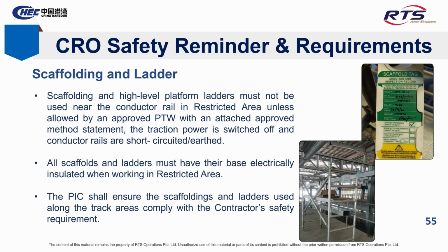Slide 55, Scaffolding and Ladder. Scaffolds and platform ladders near conductor rails in restricted areas require approved PTW and method statement. Power must be switched off and conductor rails earthed. All equipment must be insulated and comply with safety standards under PIC supervision.